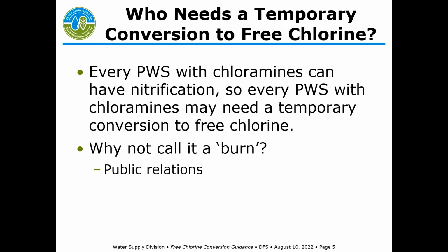So who needs a temporary conversion to free chlorine? Every PWS with chloramines can have nitrification. So every PWS with chloramines may need to have a temporary conversion to free chlorine. We at the TCEQ don't like to hear it called a burn because you're not really burning anything. I mean, you're just changing your residual.